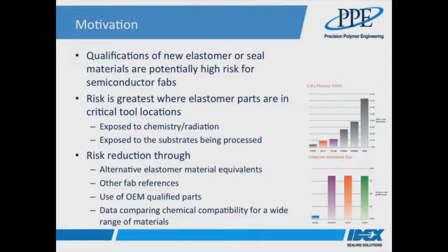Another factor to be considered is that some of the effects of the contaminant may be immediately catastrophic and therefore easy to spot. But in other cases, some categories of contaminant might create a latent defect which only becomes apparent after the part has shipped. So here I'm thinking of metallic ion contamination, where the effect on the device also depends on the type of metallic component, such as whether it's sodium or copper or some other metallic element.